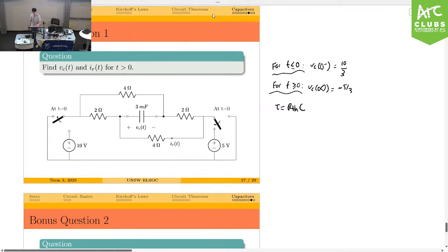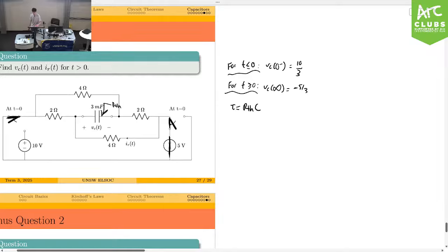Pretty much, if I want to find RTH, in this case, when this is connected and this is connected this way, to find out RTH from the middle, I can short this source. And so what the circuit looks like now is that I've got this.